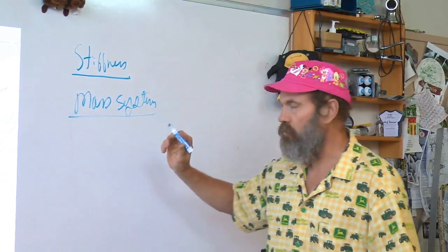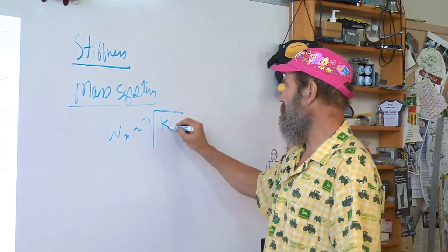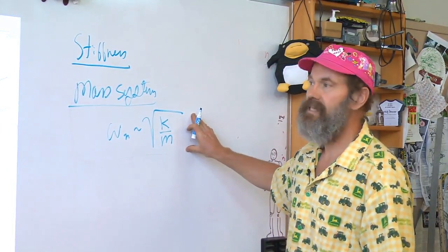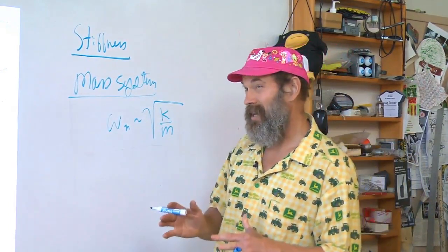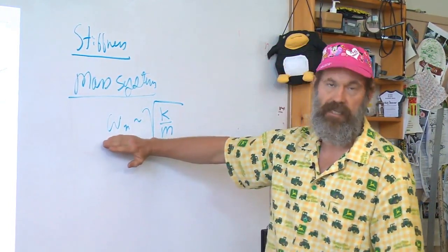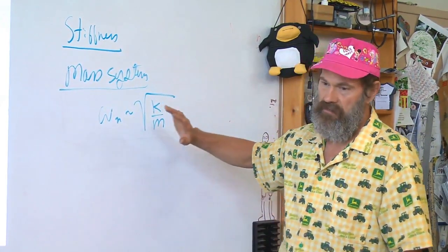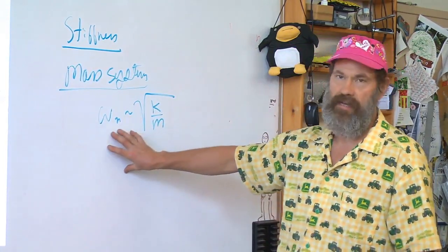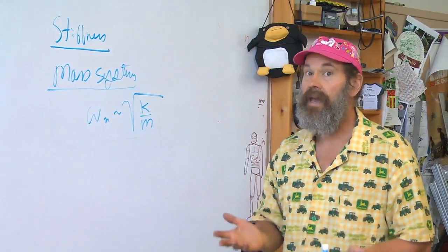So to our very first order, natural frequency goes like the square root of k over m, for just very, very simple first-mode guesstimates of, am I in the range of I'm going to have a problem or not? Well, it's going to depend upon what the excitation frequency is. And if the excitation frequency is either much less or much greater than the structural natural frequency, at least you have a hope of it being okay.